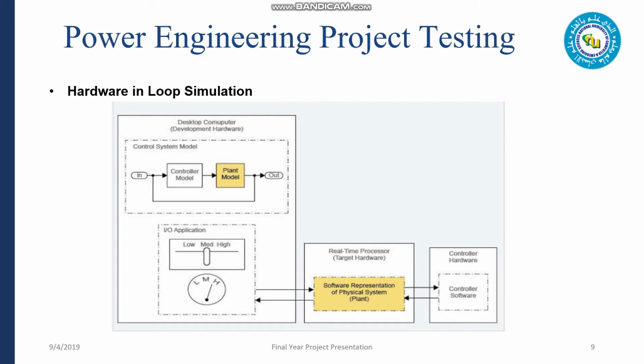Testing of control systems has traditionally been carried out directly on physical equipment in the field or on full systems in the lab. While offering testing fidelity, this practice can be very expensive, inefficient, and potentially unsafe. HIL is a possible alternative, which is a type of real-time simulation. You can use HIL simulation to test your controller design. It shows how your controller responds to real-time realistic virtual stimuli. You can also use HIL to determine if your physical system, that is the plant model, is valid. HIL testing offers an excellent alternative to traditional testing methods.